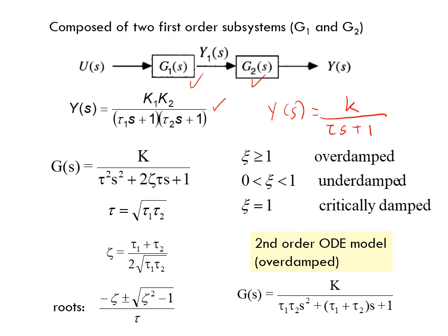The condition of stability is satisfied if and only if the damping ratio is positive. So this is the damping ratio. We can now see that the term damping ratio refers to the damping of oscillation. The behavior of the response is as follows. If the damping ratio is larger than or equal to 1, the response is categorized as overdamped.